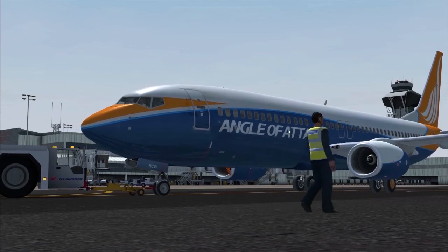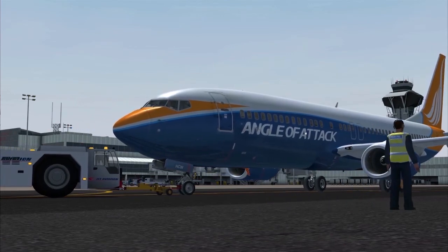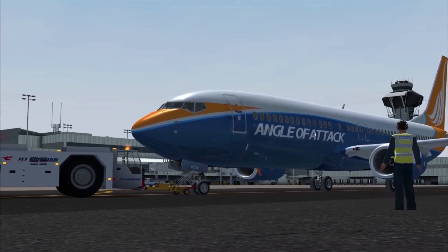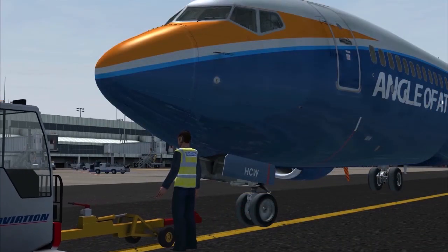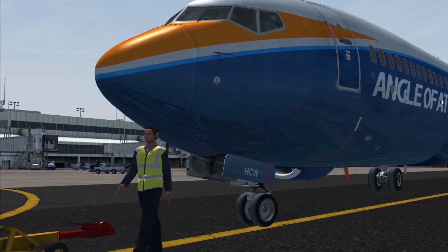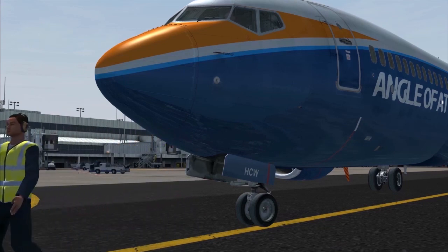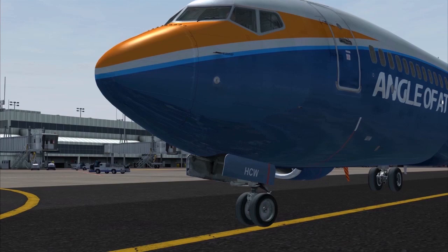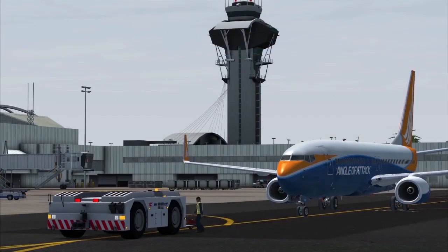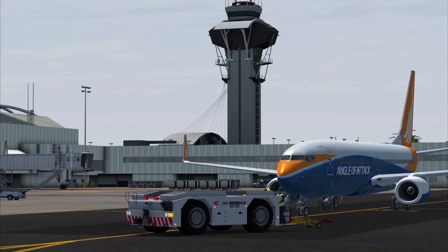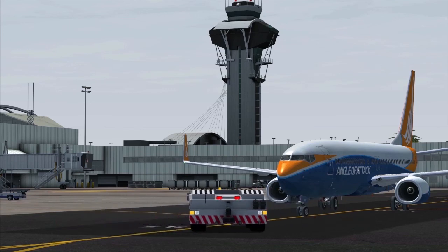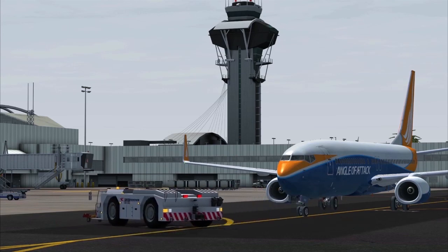Earlier on ground, highly pressurized air provided pneumatic power that was later converted to mechanical energy in order to turn the N2 shaft through the accessory gearbox. This high-pressure air is called bleed air, and we'll be discussing it in detail in the air systems lesson. However, we must know that during a ground start, bleed air is obtained from the APU. When the APU is inoperative, an external power unit may alternatively supply high-pressure compressed air.